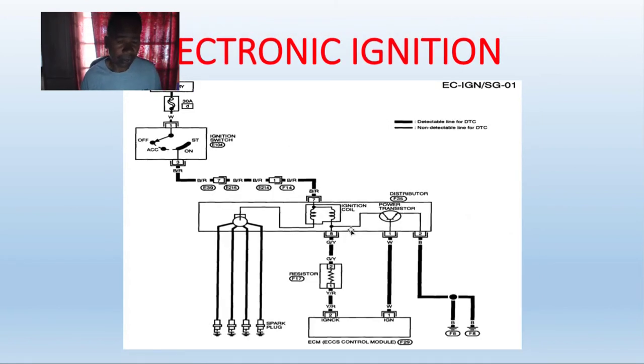Now that's what's old school. The newer vehicles obviously don't use points. They're replaced with either the PCM or the ICM, the ignition control module. So in today's cars, the points do not exist. The points were replaced with the primary ignition control module, or the PCM does the triggering.